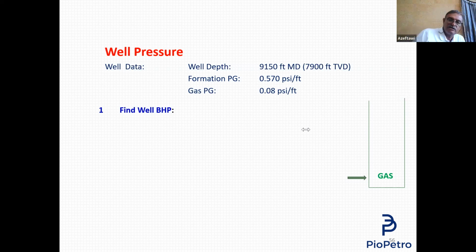The pressure gauge doesn't know calculations. He learned when he was a kid. He will go to the highest pressure. This pressure gauge on top of the manifold will read 400 psi. None of the other compressors will work.